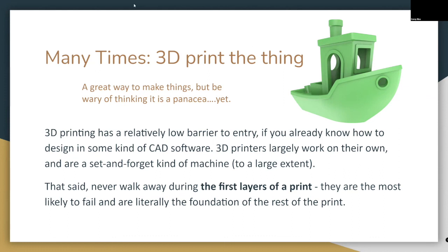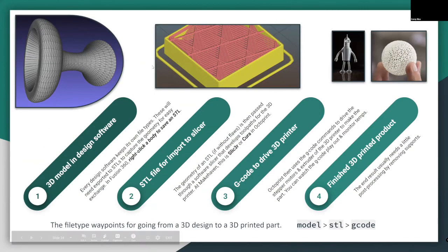You're totally able to walk away from a 3D printer once it's running, but I would definitely recommend that you don't leave until the first couple layers are down. You just want to see that it's got good bed adhesion, that it's got a good start. And if it's going to fail, it's better to stop it early and then try again rather than figure that out after you've invested a few hours in it, and then filament that you've wasted.